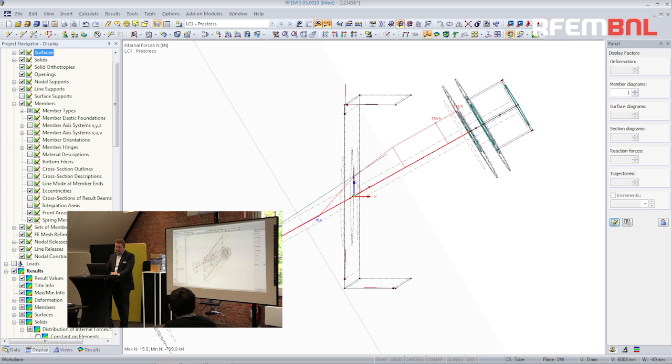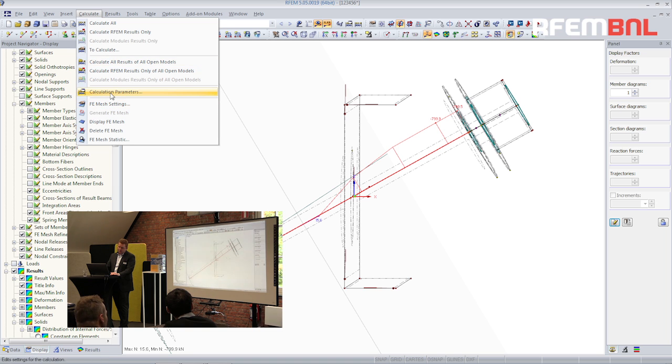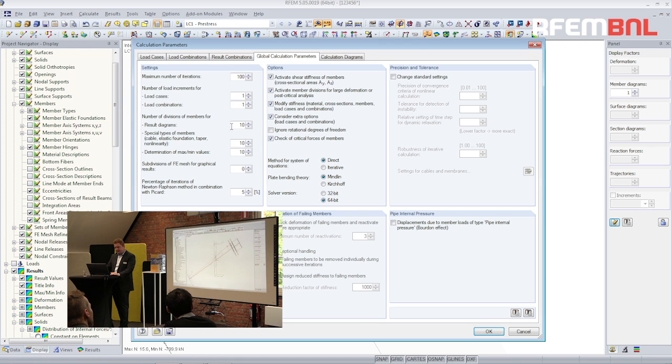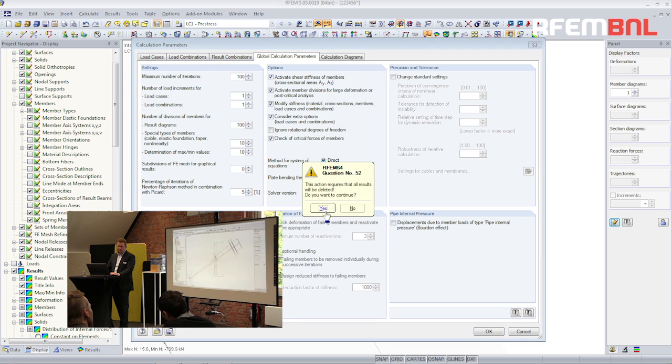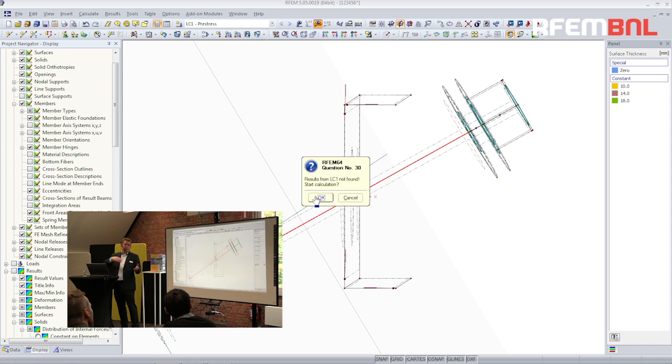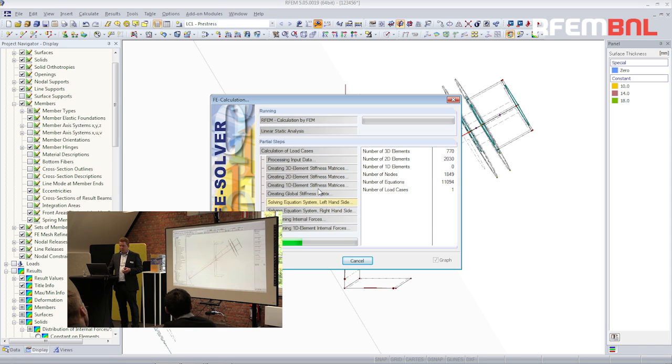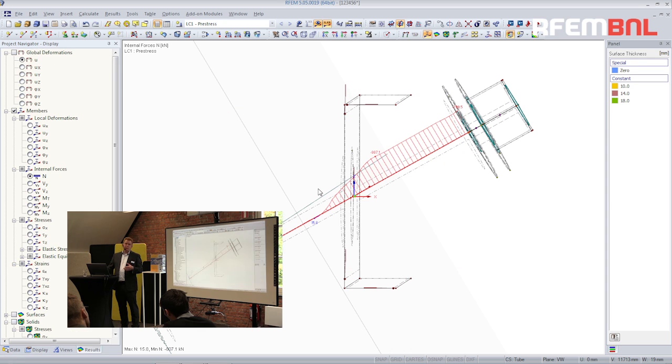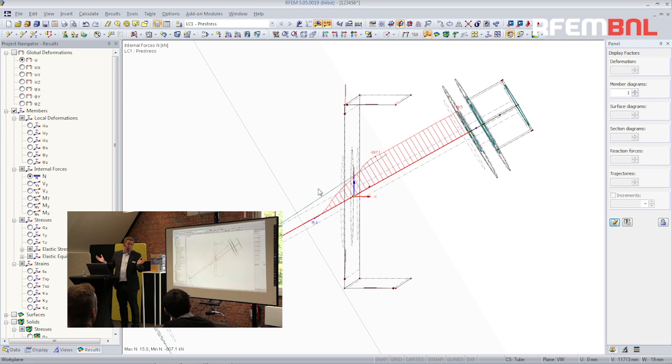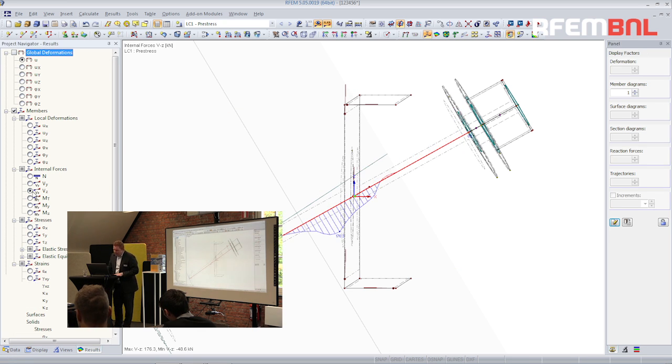And if I go to transparent mode, for instance, the introduction of the normal force, and I turn off all the nice meshing and all the nice but not so important surface support, you see there is a normal force here. And you see along this line, it's about 800, yeah? And it is introduced in this area to 0. So it means that the complete pre-stressing was in the tube here. There was first in the solid, then in the tube. And then somehow it transfers. In effect, it goes to the boundary supports. That's what is happening. I think this is quite coarse.